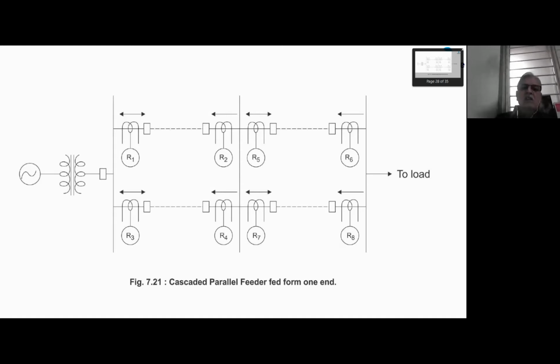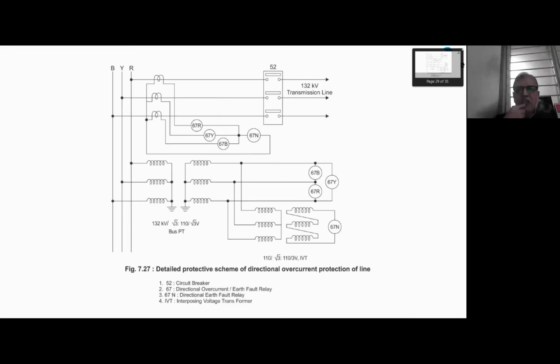One has to go for computer algorithms, because iterative calculation is required, and many people are doing research work on it. Even then, it often happens that at a certain fault location, the primary relay does not operate, nor the backup relay, and some third, unrelated relay operates. This is known as sympathy trip, and people in research are trying to reduce sympathy trips.